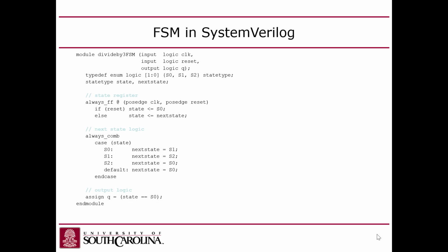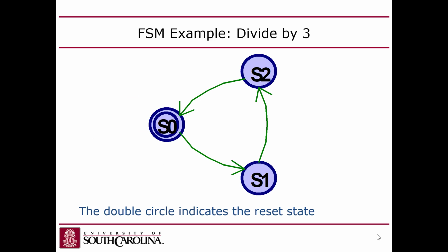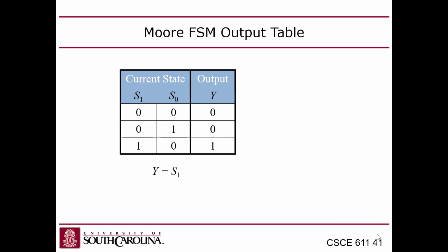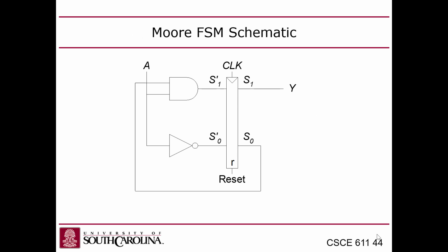Okay, now the other thing you'll notice is there's this syntax at the top where they declare an enumerated type for the state. This is one of the things they introduced in System Verilog that didn't exist in Verilog. In Verilog, as a Verilog programmer, when you design a state machine, you had to